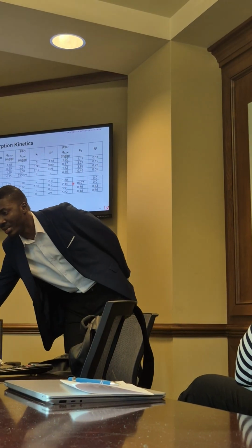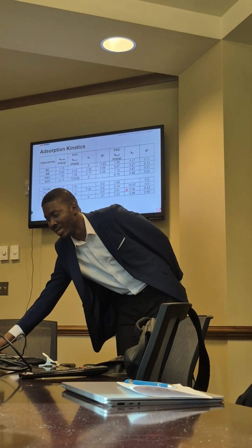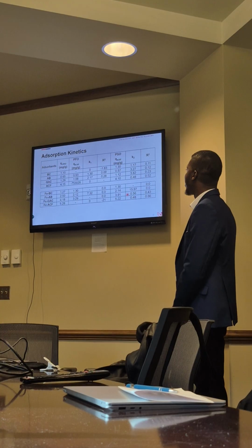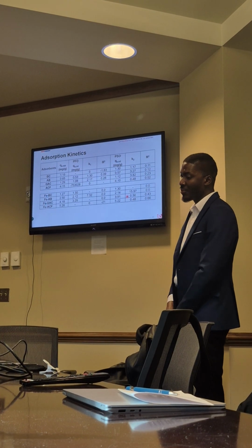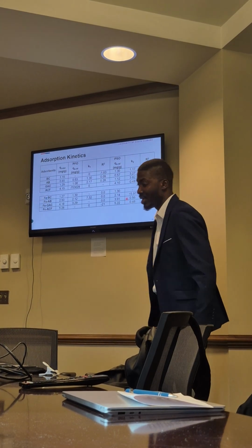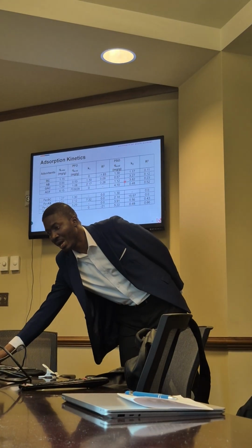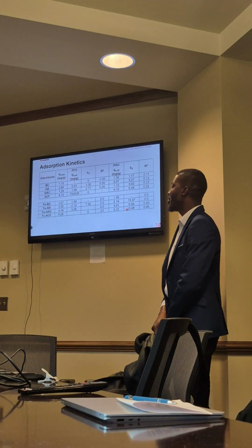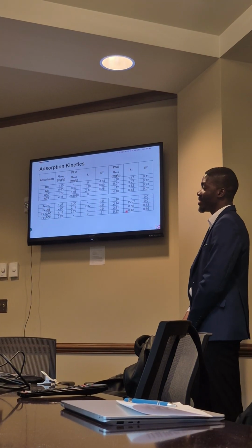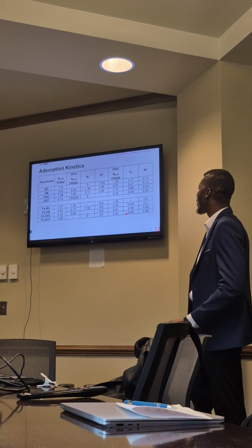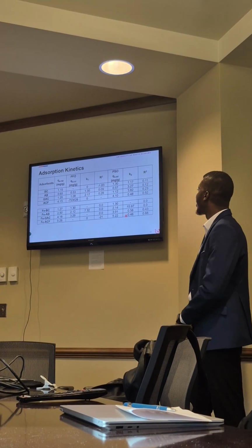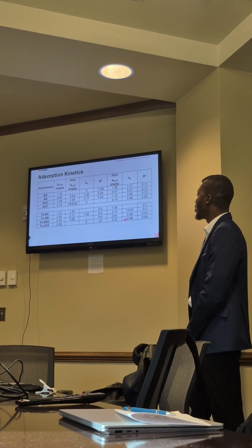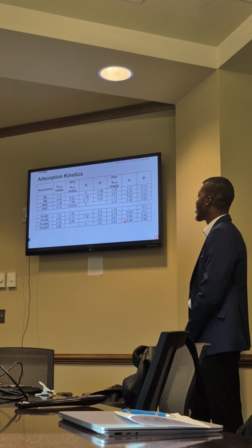GAC's rate reduced after iron modification, and this also signifies that some of the pores were interfering with the arsenate removal. ACF, on the other hand, had the same rate constant between the iron modified and the raw material. This signifies that even though we had pore blockage, ACF had its fibrous forms and was evenly distributed in our water, hence attracting arsenate ions.